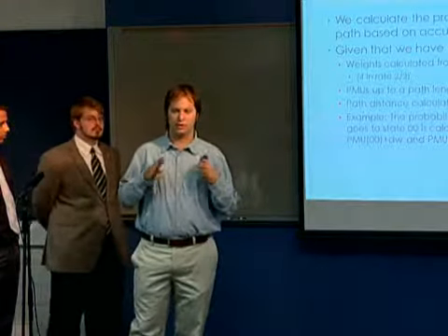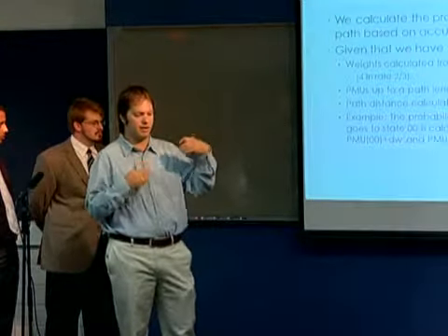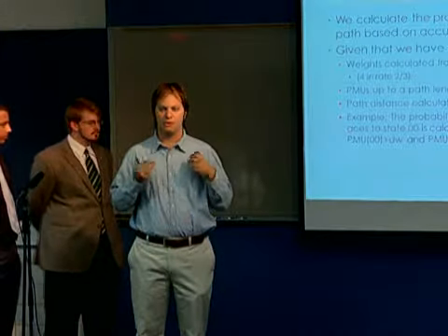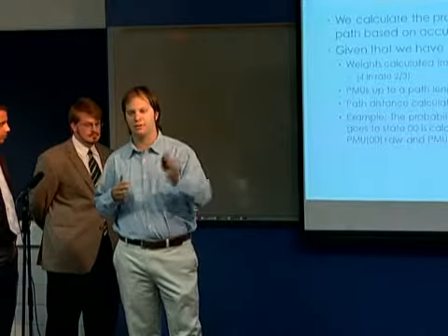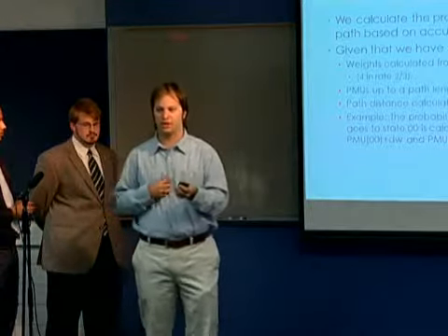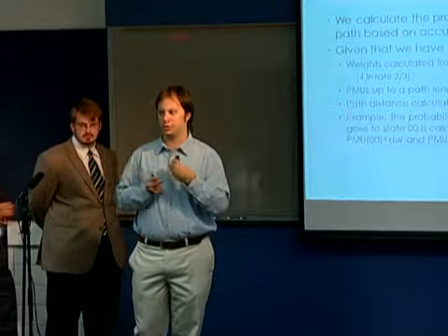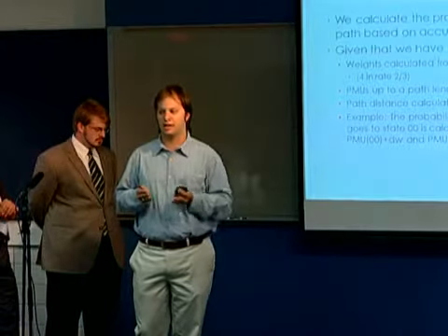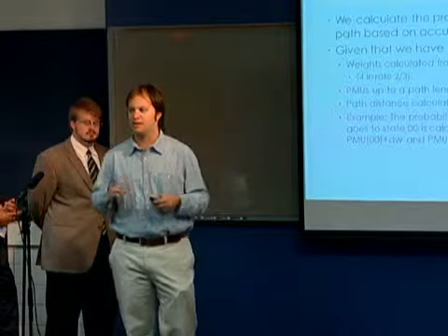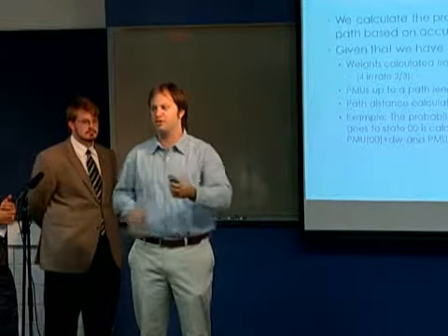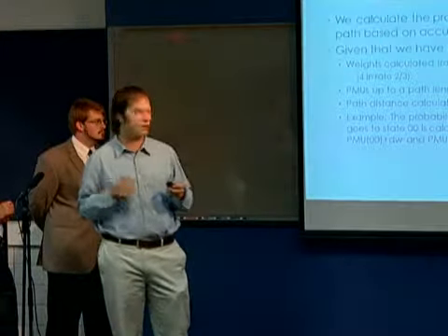We can then use these weights to determine probabilistic weights at each point going through a trellis, because our eventual goal is to find the path through the trellis that our encoder took, and by doing that, we can weed out local mistakes, because we can see more than just one transition. We can see multiple transitions, and since each transition is dependent on the transitions before it, that gives us additional information that's going to give us the strength of our decoder.